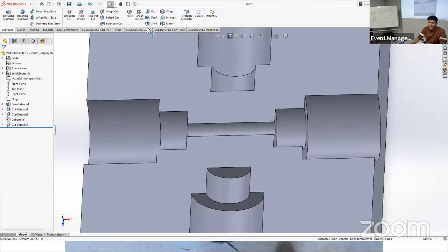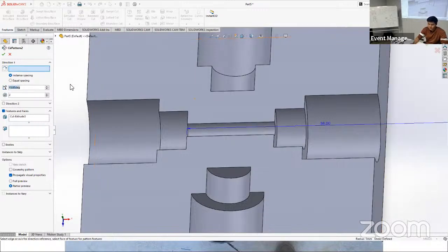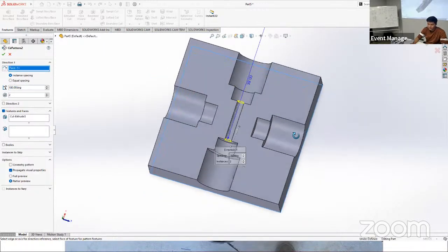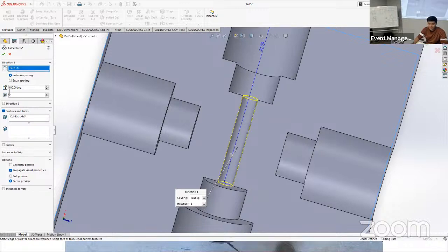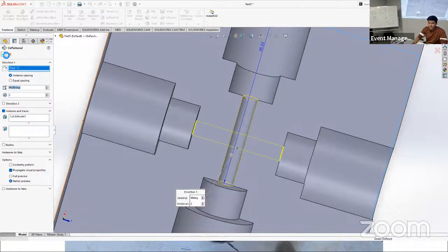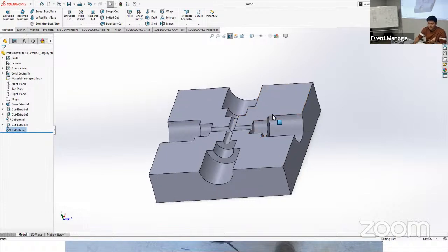And we can also duplicate that very easily by pointing at that plane and making a circular pattern again. And this time it's going to be the second one, and the angle is going to be 180. And it's going to be around that plane. Okay, 180 is too much because it just flips it. Let's give it 90. Okay, right now we have our connector.